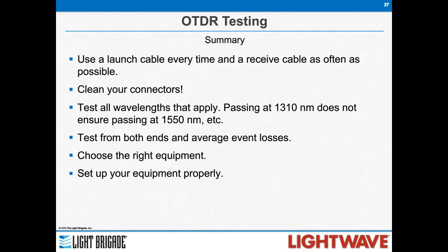So in summary, we talked about launch cable, receive cable. Those are two important things to get accurate results. Clean your connectors, clean your test cables so you don't transfer bad dirt and damage onto whatever you're testing. Make sure you test all wavelengths that are going to be used, particularly in single mode.